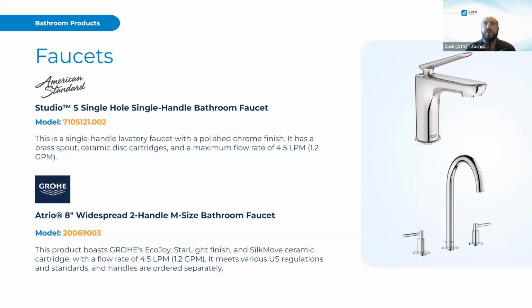So one thing that we'll notice with the flow rate for WELL certification is it does require a certain amount of flow still. We're quite often asked, can I meet this standard and still get my 0.5? And it's simply incongruent. For these private labs, your design point for LEED is 1.5, so a 1.2 is still providing savings. And this is providing savings while meeting the design standard of an adequate wash. So that's an important thing to consider.